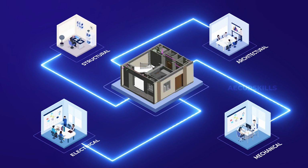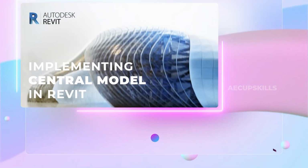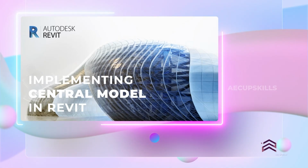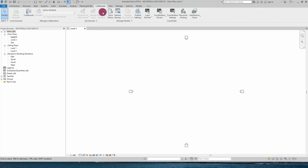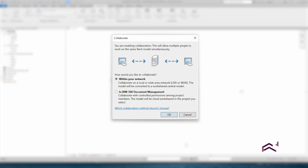Since we have explained the basics of a central model, we can learn about implementing the central model in Revit. After we open our Revit file, we go to the Collaborate tab. Here, we click the Collaborate button, which opens up the option to enable work sharing.